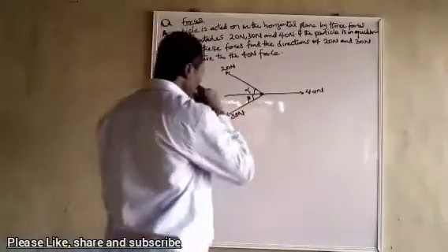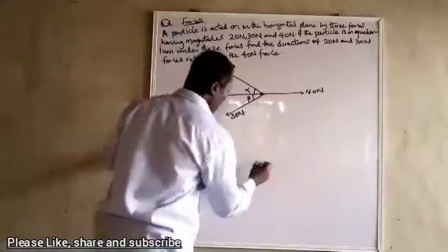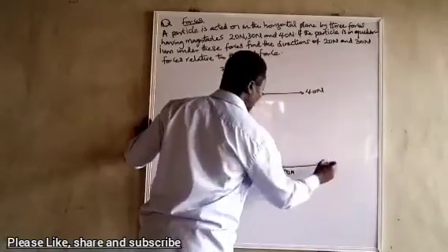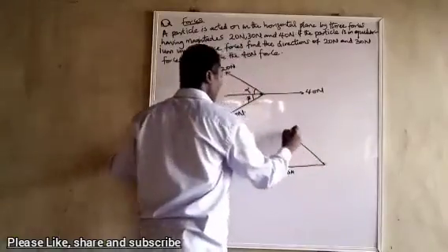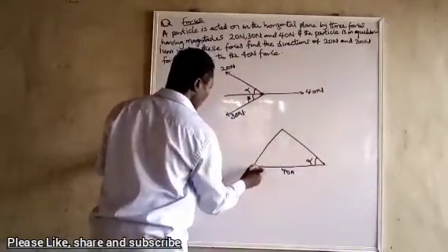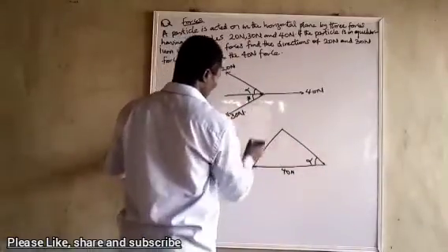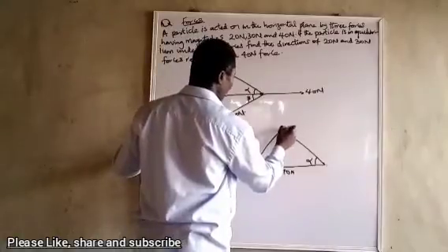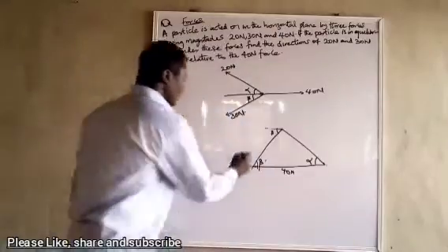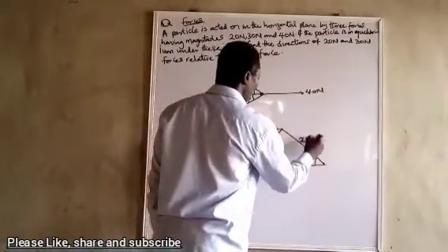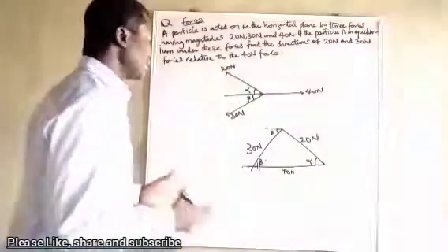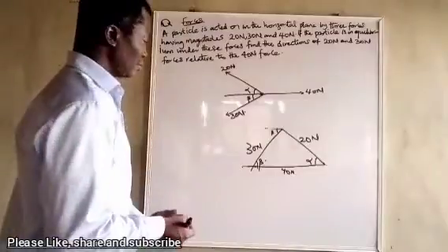So let's try again by drawing the complete force triangle. So we have something like this. Triangle, sorry, 40. And like this, the 20 will go up like this, and we'll subtend alpha there. And the 30 will come like this. If you look at it, this place is beta. So this place will be beta. And this is 30, and this is 20. So it's in equilibrium because that's closed now. To find these angles, it will be very easy if you at least start with the cosine rule.